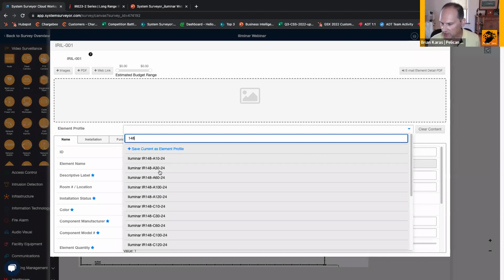In a lot of the outdoor scenarios, we see those 12 volt DC or 24 volt AC powered units. Indoors, especially for shorter runs, PoE is a very common choice for cameras these days. So we have PoE powered units as well. So you can pull another network cable to wherever you're going to put the indoor illuminator, plug it into your PoE switch, and the illuminator will get power from that, just like a camera.